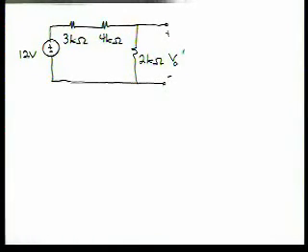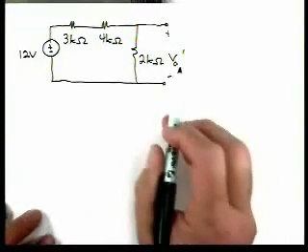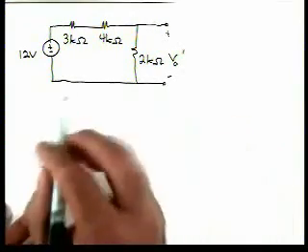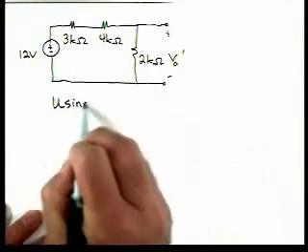We've taken the current source and replaced it with an open, or we turned it down to 0 current, which is characterized as an open circuit. So we now need to calculate the contribution to the voltage V0 from the 12-volt source, and we can do that using voltage division.